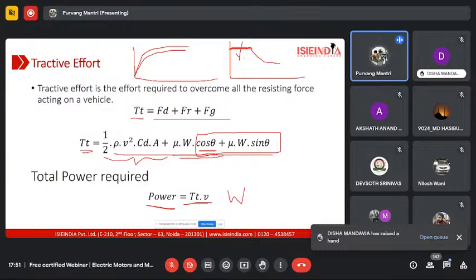But yeah, the person had shown that the gear shifting was pretty easy. There were no torque issues, or the driver didn't even need to press the clutch while shifting the gears, because whenever you lift your foot off the accelerator pedal, definitely the motor is not going to provide any torque to the transmission case, and in that way, the shifting can be done without pressing the clutch pedal. So yeah, you can provide multi-speed gearboxes with your electric motors depending on how much torque is required, and you can use it to your advantage.